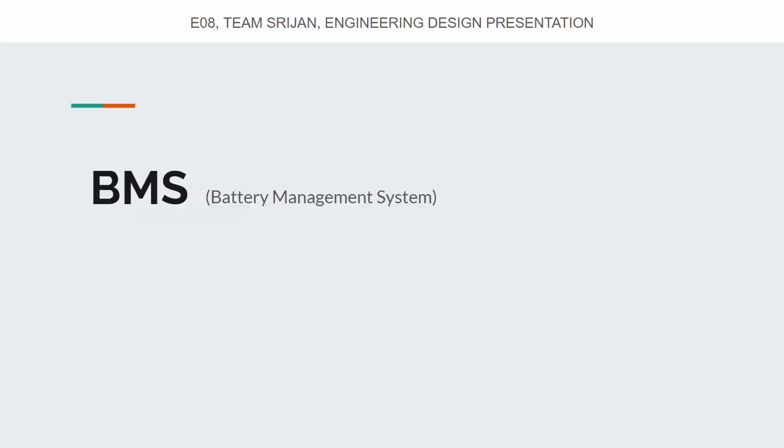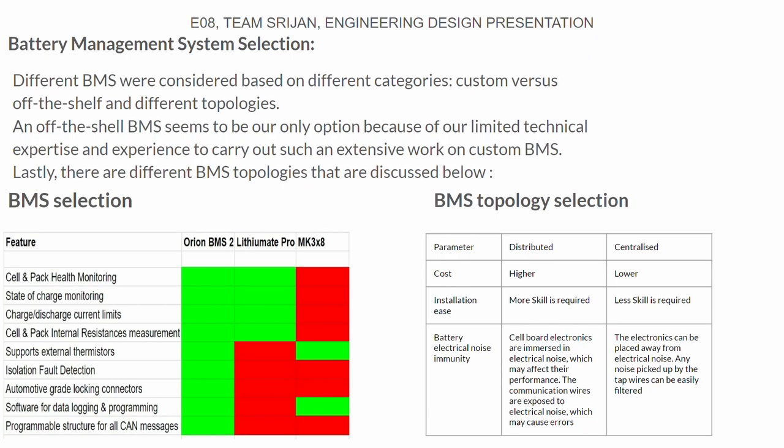Battery management system selection. We opted for a centralized BMS system over a distributed one primarily for 2 reasons. It's easier to install and the overall cost is lower.